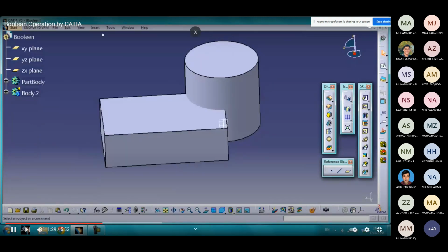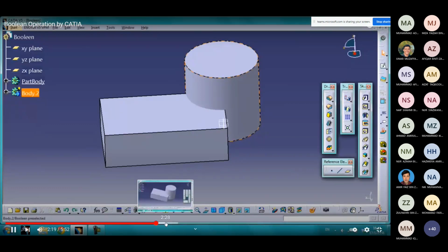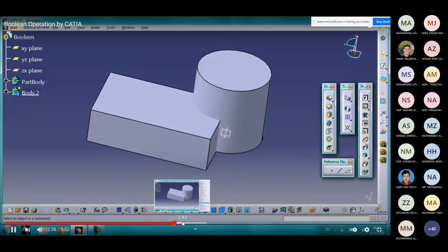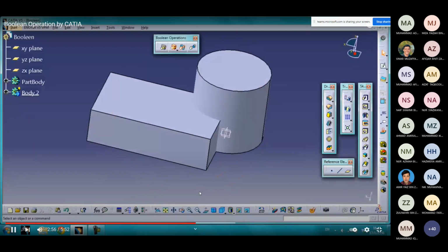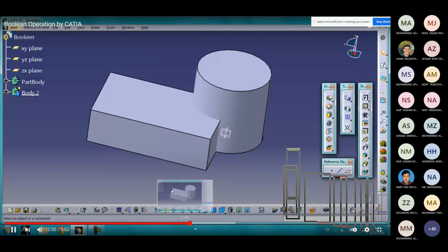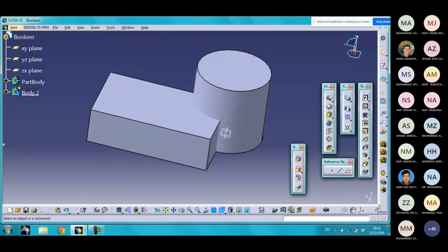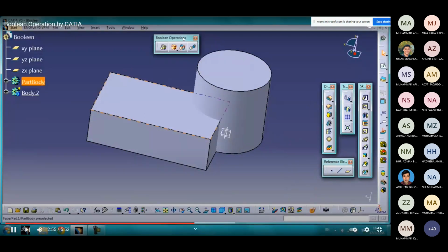All right. Next, if you want to use the Boolean operation, they will go into, let me fast forward it. So we're going to actually see this in the lab ourselves. So Boolean operation is a toolbar over here, which you can actually extract. Under Boolean, they have add, they have remove, they have intersect.